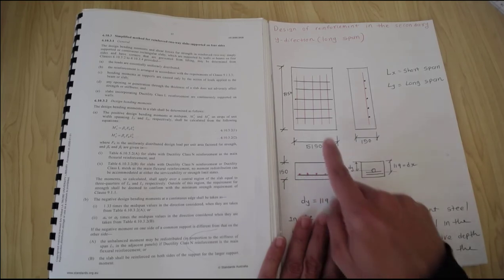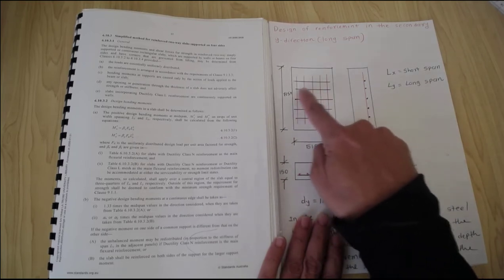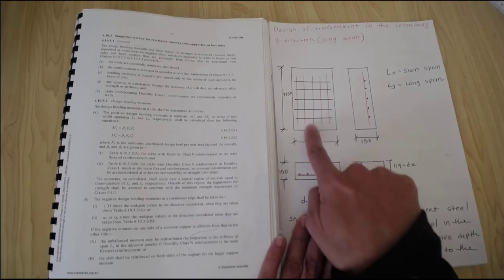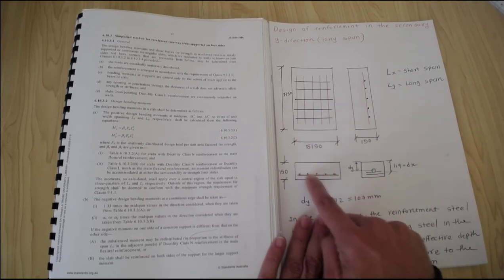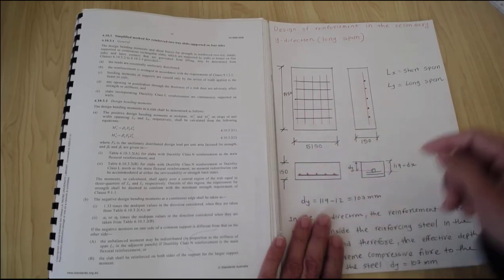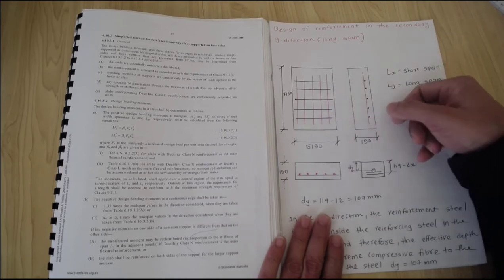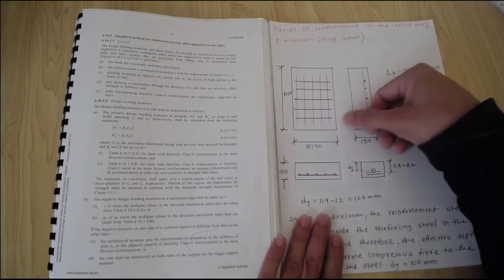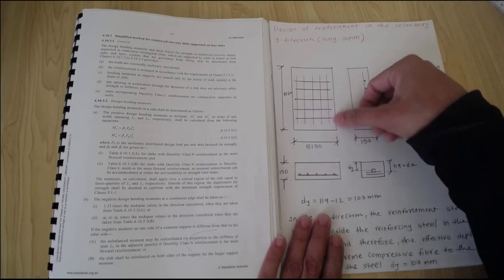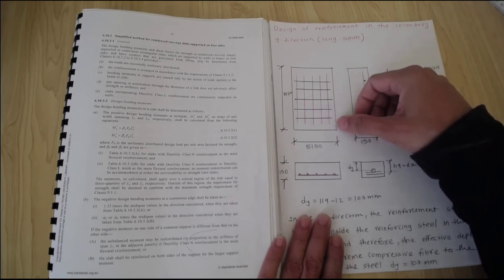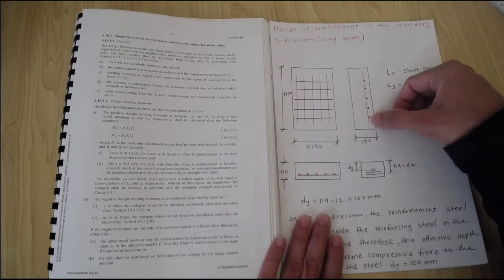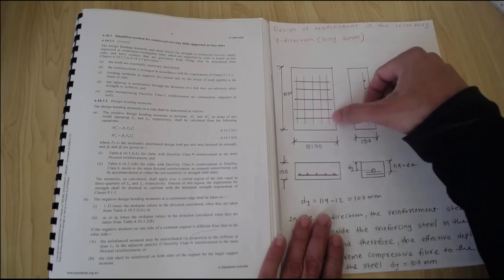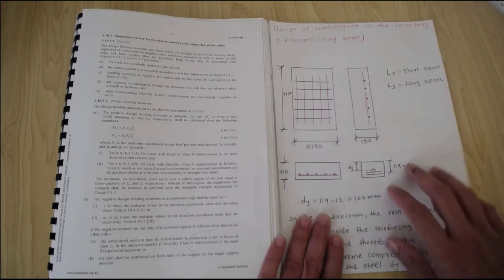The first is primary, and then the second layer comes as a secondary reinforcement. So this is the primary one, which is the blue one, which I can show you here, and these red bars that are dots when I see them from here, that is the secondary bar. When I look from this side, I would see these dots that are my primary reinforcement, the blue one along the short spans, and then you have these reinforcement, these are the secondary reinforcement.